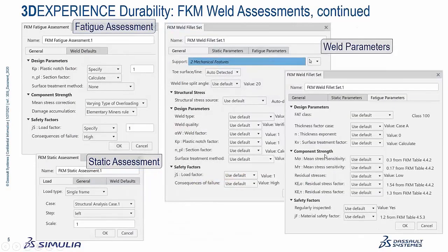I think most companies are either FKM style approach or non-FKM style approach. If you're FKM style approach, you understand that the FKM guideline has a lot of control parameters that you can play with. In an earlier release of FKM capabilities for base metal fatigue, not for non-welded structures, in FESafe, we thought most people would take the default lookup tables and so forth, and that turned out to be wrong.